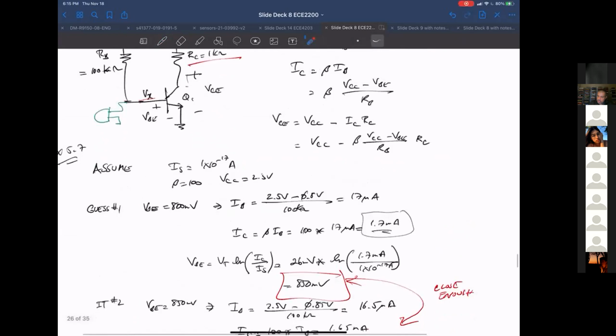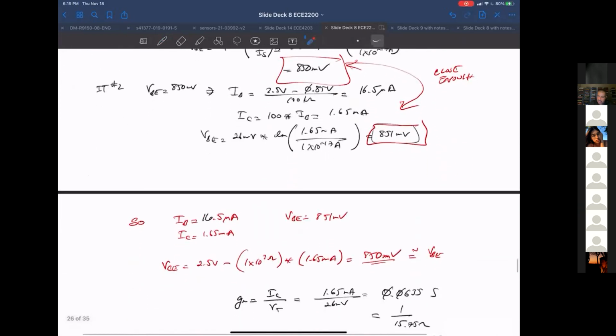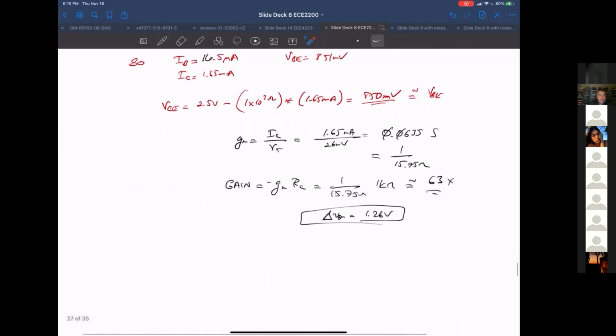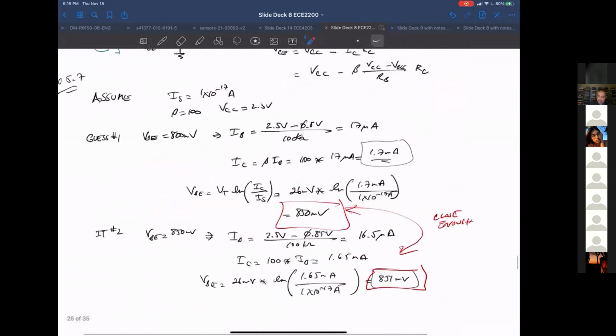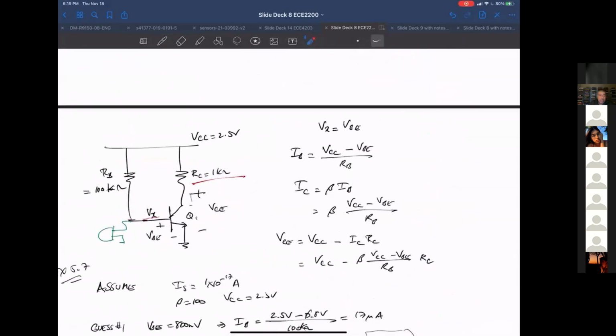But of course, I only say that because it's not. And why isn't it? Well, the reason is this is an example of something you can get working in the lab, but not in production. In the lab, you've got a single bipolar transistor. You know what the beta is. You can tweak this resistor R sub B to get the right I sub B going through it, and get this at the right value.